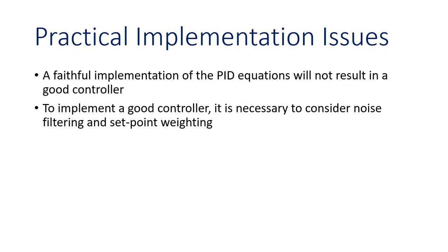Now, there are some practical implementation issues in PID control tuning, or implementing the equation. The first one is that a faithful implementation of the PID equation will not result in a good controller. To implement a good controller, it is necessary to consider noise filtering and set point weighting.